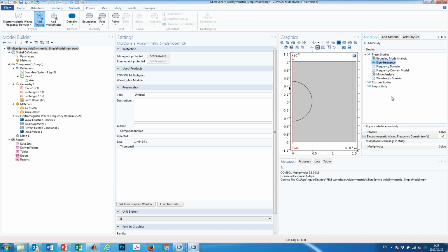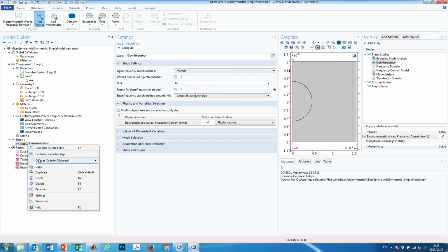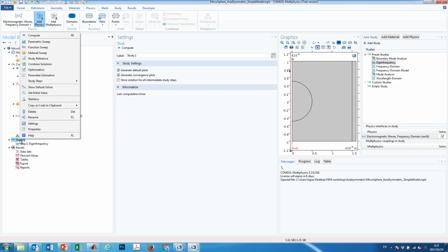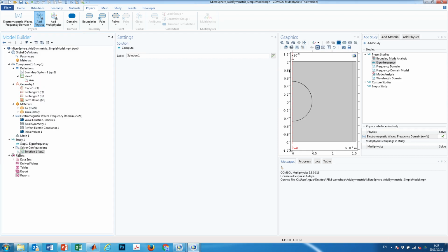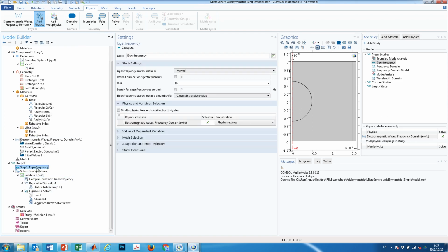Under here, we look for eigenfrequency because, as explained, this is a cavity system. You define the mode index, and you're looking for the amplitude together with the eigenfrequency. So under this, you can also ask it to show you the default solver, where there are more configurations inside. So for eigenfrequency, you can set the number of eigenfrequencies, let's say 5, or by default 6 is okay.